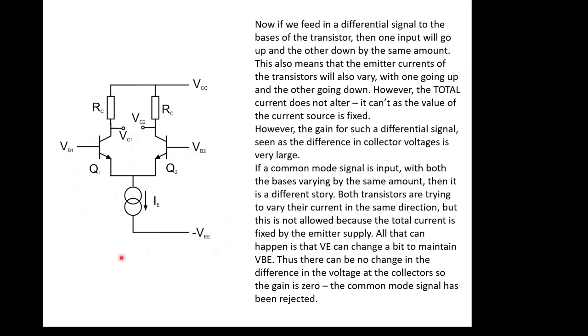So as long as you can arrange for your signal to be differential and most of the noise to be common mode, this actually acts as a really good filter and is a good way of getting rid of lots of potential problems, particularly in factory environments.